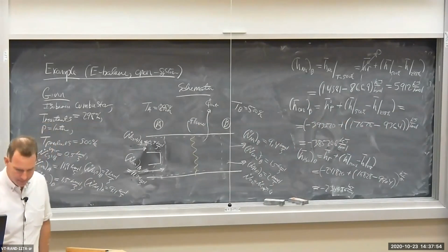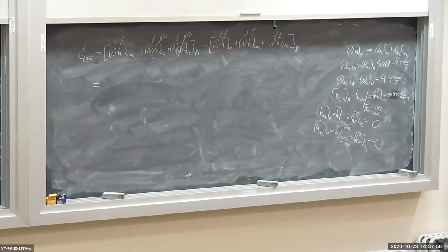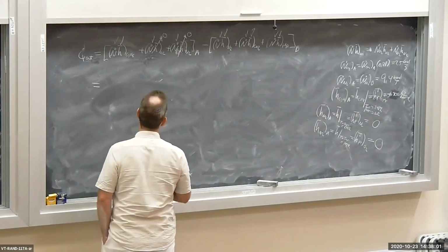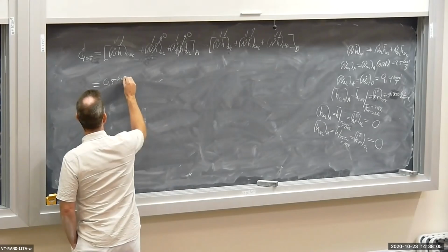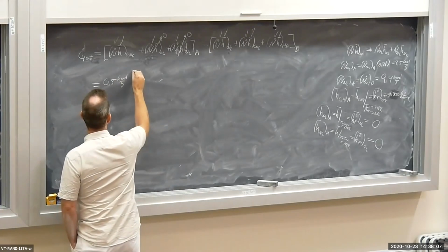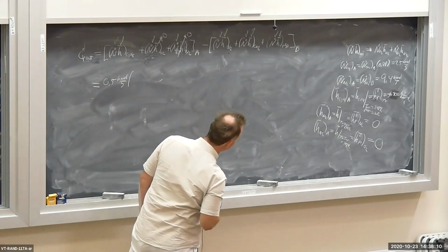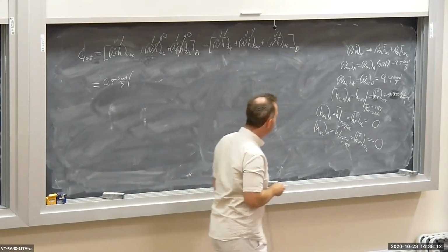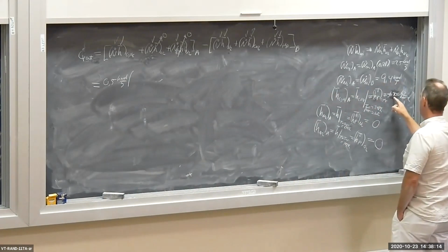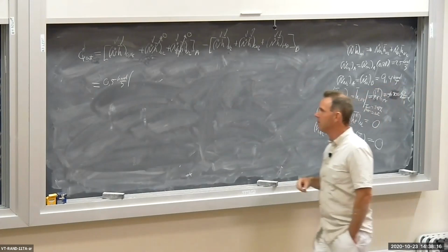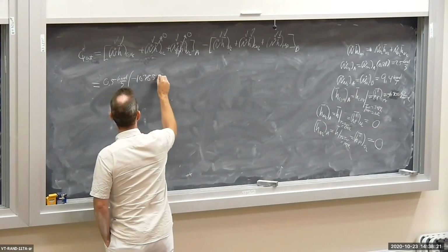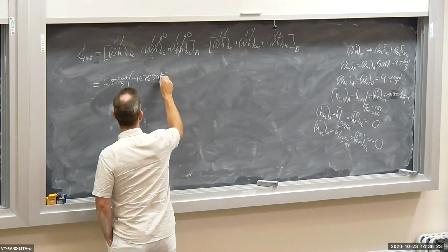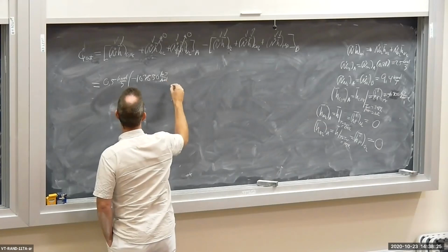Let's plug in. N dot for the C3H8 at the inlet is 0.5 kilomoles per second. The H bar of the propane is negative 103,850, and that's going to be kilojoules per kilomole.